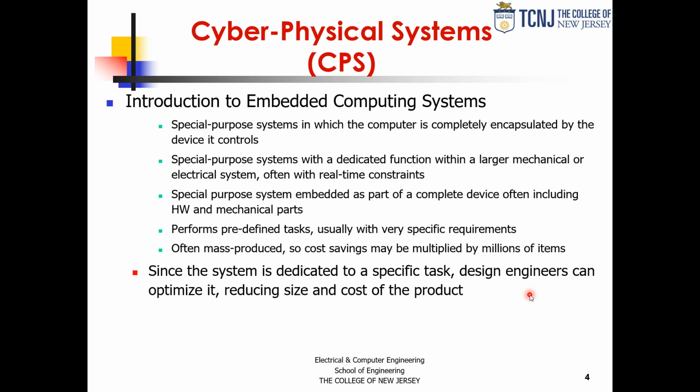So in that case, if you do hardwire it with an FPGA, that's the extreme of having a specific task, a specific functionality, and you may have some ability to configure it, to program it to a certain extent, but compared to something where you write VHDL or Verilog to get the functionality versus something where you write a C program, there is a big difference in flexibility there. But there is also a big difference in performance.